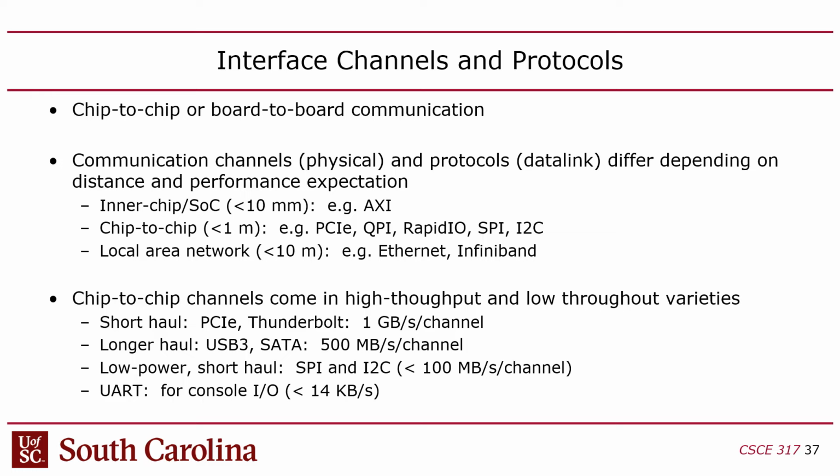Now let me talk about the hardware perspective. I talked last time about interface protocols, how hardware communicates. There's a lot of different ways to do hardware communication, and a lot of that depends on how long the channel is. You have one type of communication between peripherals on a chip, happening over millimeters, and then another set of protocols within a circuit board between chips. Then you have another type within modules in a computer, going across edge connectors and PCI connectors from board to board, right? And then other protocols that go between computers, like on a network, through network cables, right? So the distance that the signals are traveling plays a big part of this.